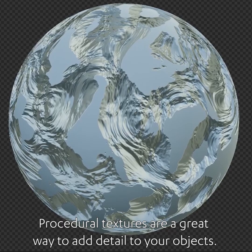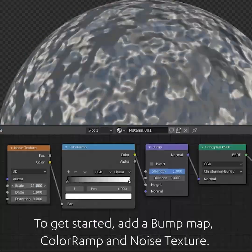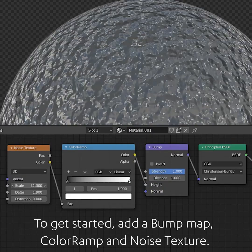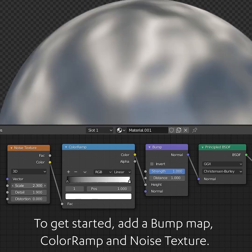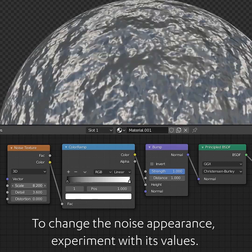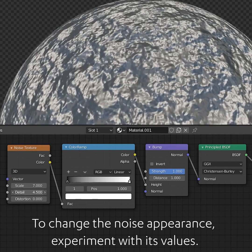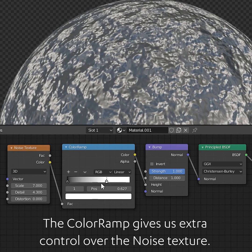Procedural textures are a great way to add detail to your objects. To get started, add a bump map, color ramp and noise texture to the material. To change the noise appearance, experiment with its values. The color ramp gives us extra control over the noise texture.